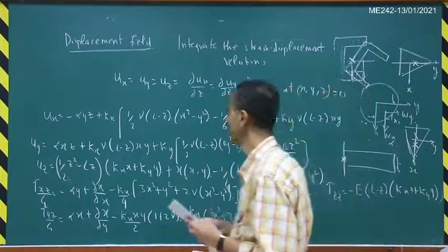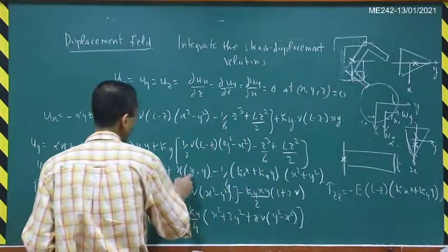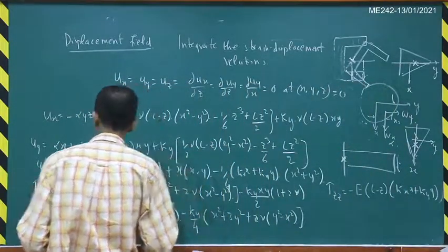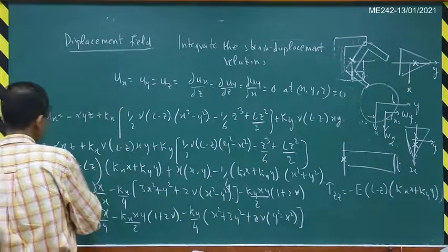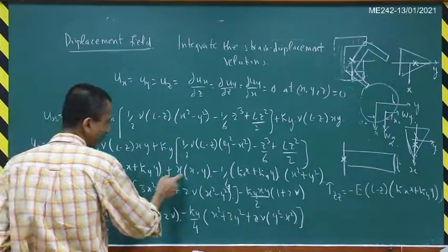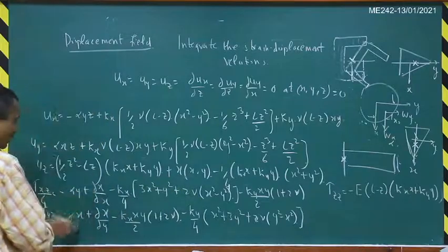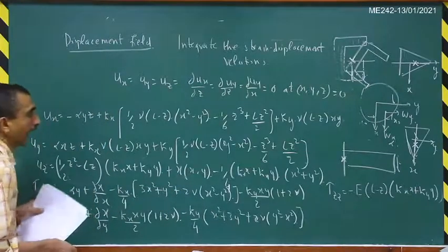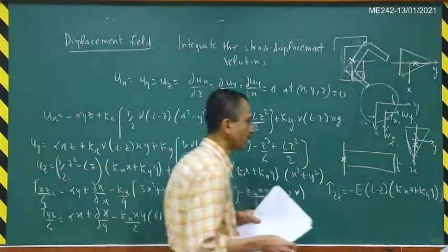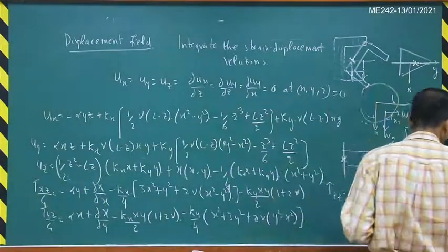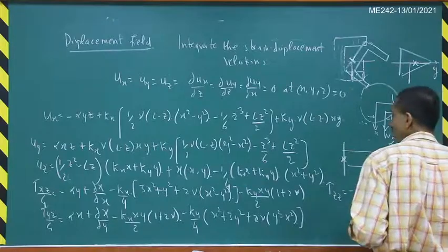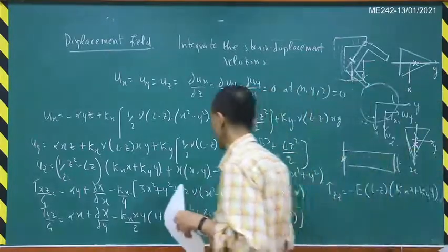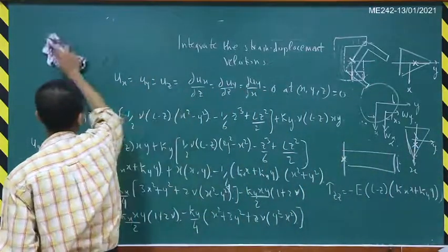So you can see that this new function has now entered into the formulation. So the displacement uz is dependent on this chi and also these stresses. The tau xz and the tau yz are also dependent on this function chi. So let us now talk about this new function that has been introduced. The governing equation for this new function chi is just, it's a harmonic function.